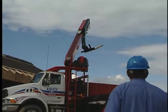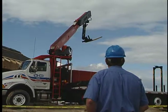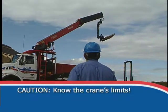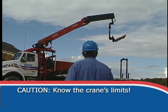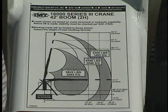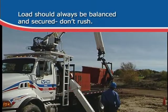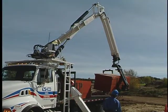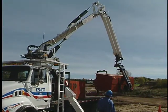Here are a few operational and technique reminders and cautions. Know the crane limits. Check the crane's load rating chart. Those limits should never be exceeded. Load should always be balanced and secure. Never rush to complete a lift because the load is improperly balanced or secured on the fork.